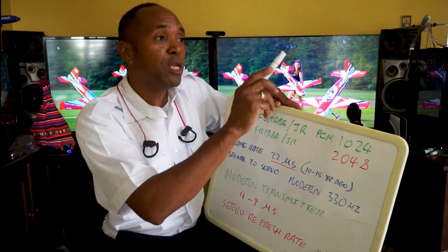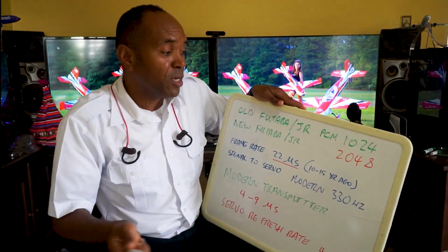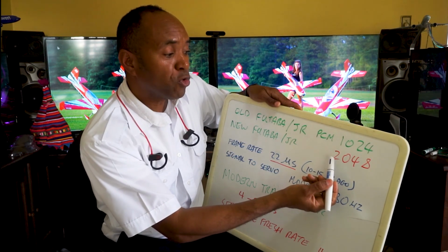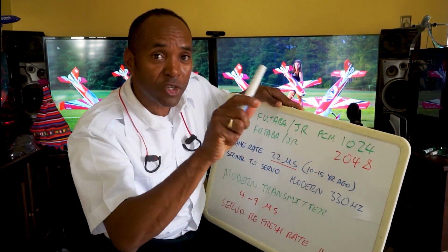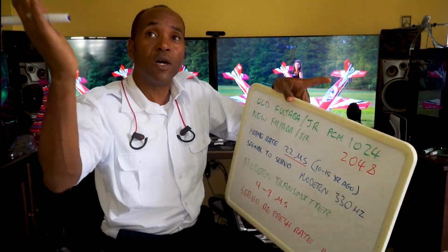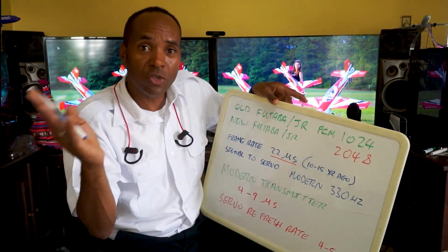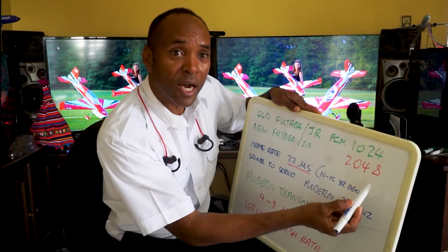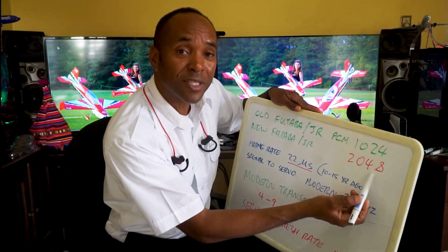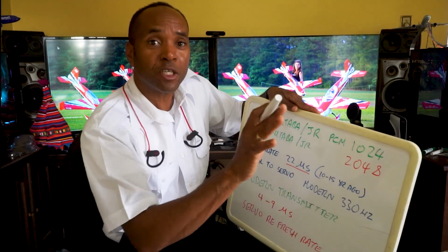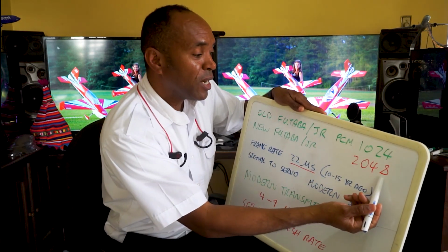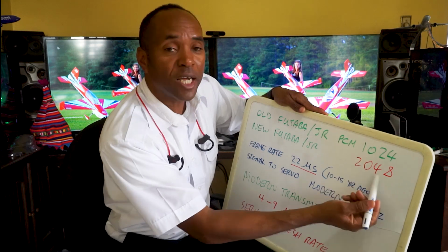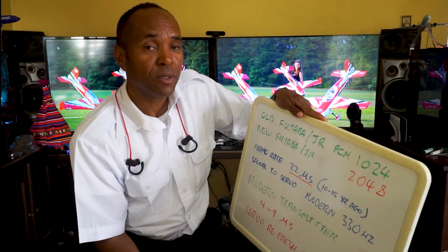So therefore, within 120 degrees of swing, the servo has up to 2048 command steps to make, of which only 120 degrees is usable, right? Digital servos are able to make use of this high resolution. The old analogs may not be able to interpret this kind of resolution so well, right?